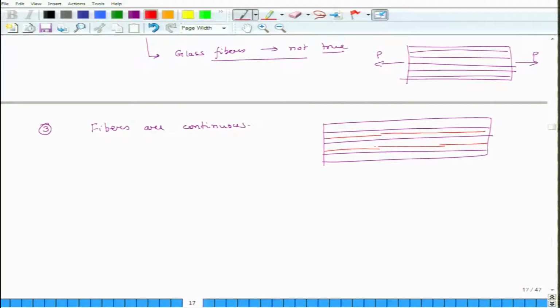Something like this. So, there will be broken fibers. There may be still long fibers of sufficient length, so that we cannot call it a short fiber composite, but there will be some breakages because of processing, also because of production. When this happens, at their end points, you have sources of stress concentration. At the end points, there are higher stresses than what you will be predicting.